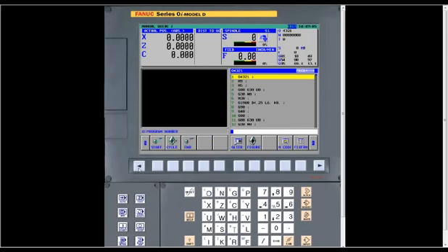Oh, yeah, that's no problem. I mean, when you're doing a turning cycle with a hollow cylinder, say you're boring out the inside of it, the last move that you would make would actually go down to the smallest size of that hollow cylinder, and then the control would know that that was where the stock would be removed. So it's very simple to do that. It's just based on the geometry that you described for that hollow cylinder within the turning cycle. That's how you do that.